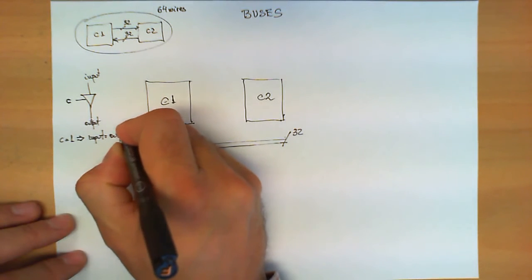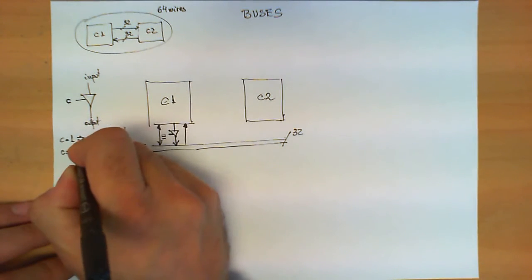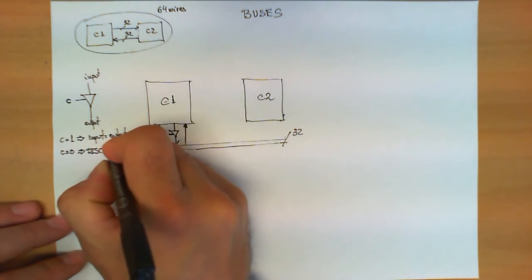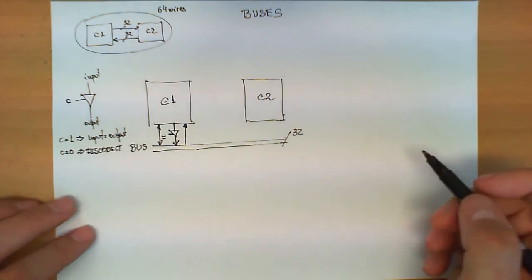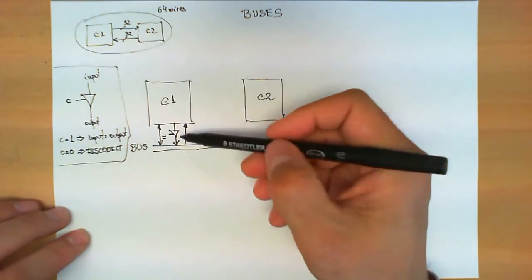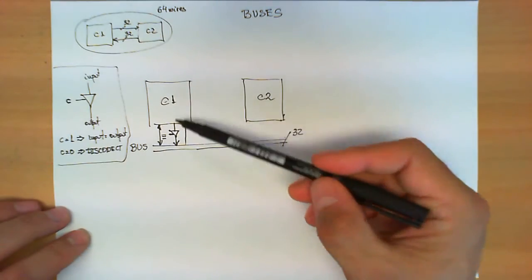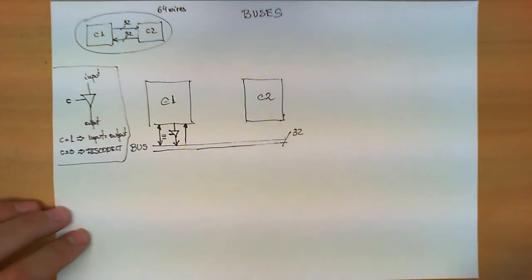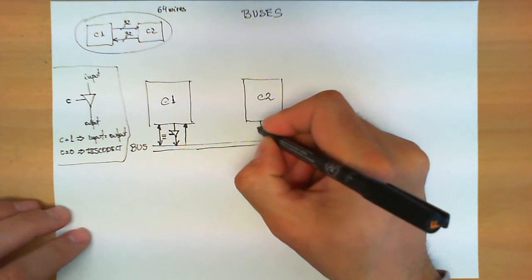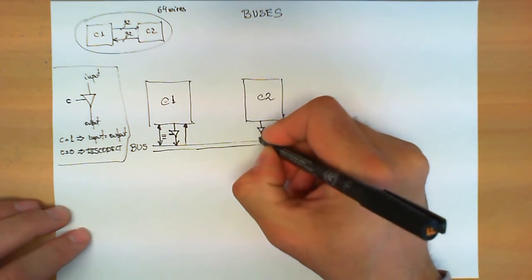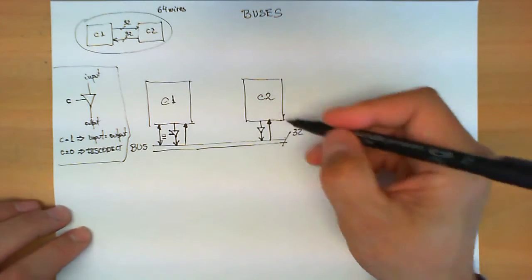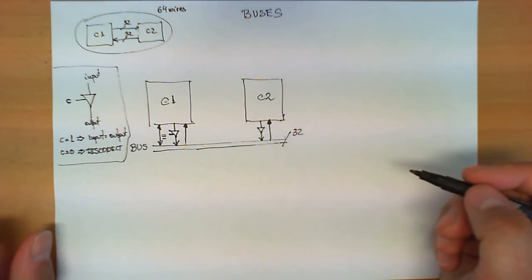If C is equal to 0, and this is the most important part, we have a disconnect. So this circuit offers us the possibility of connecting and disconnecting this circuit from these 32 signals. Now let's suppose we have exactly the same situation here. We have one of these control signals to write into the bus and one for reading from the bus. So now let's think in terms of these four communications.